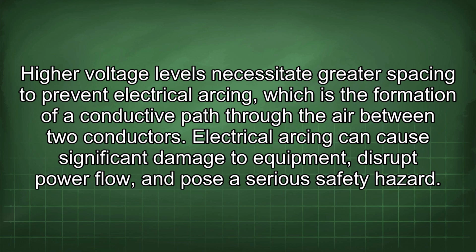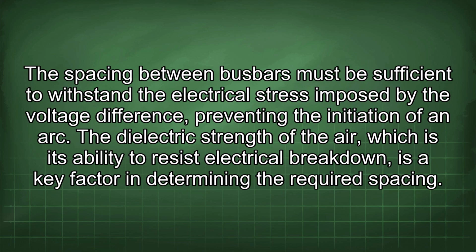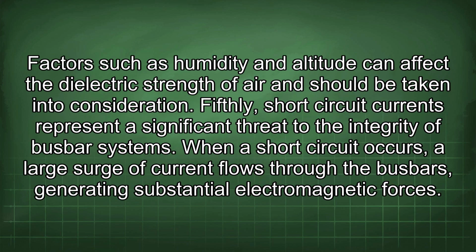Electrical arcing can cause significant damage to equipment, disrupt power flow, and pose a serious safety hazard. The spacing between busbars must be sufficient to withstand the electrical stress imposed by the voltage difference, preventing the initiation of an arc. The dielectric strength of the air, which is its ability to resist electrical breakdown, is a key factor in determining the required spacing. Factors such as humidity and altitude can affect the dielectric strength of air and should be taken into consideration.